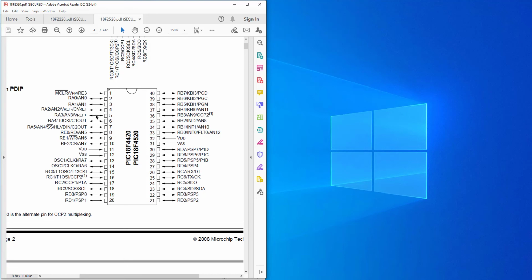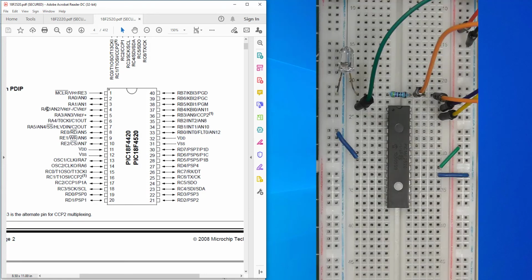So for now what we are interested in is we're gonna have our port C in here. We got RC0, 1, 2, 3. Now we have to be careful because now this is a port D now. So RC4, RC5, 6 and 7. Okay, so that's how it is. Now these are the connections, power supply connections to the PIC as well. So what we see here, we've got the double negative and we got double positive, and that's how we're gonna connect it now. So let's go to our board.